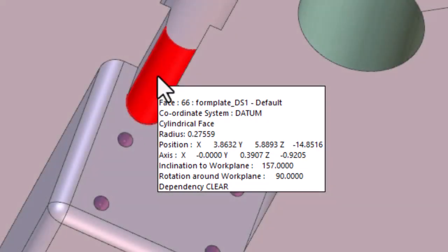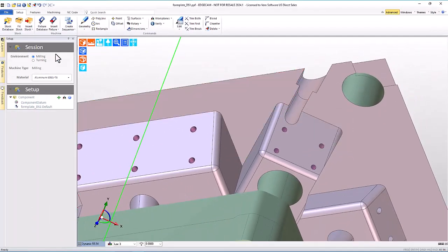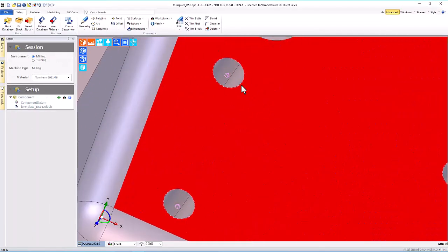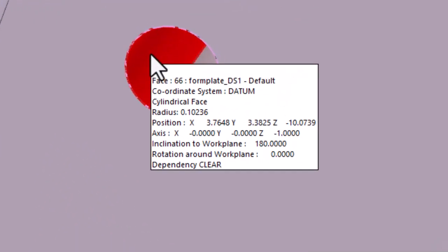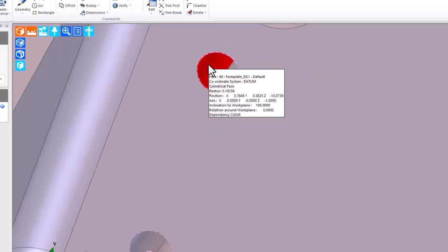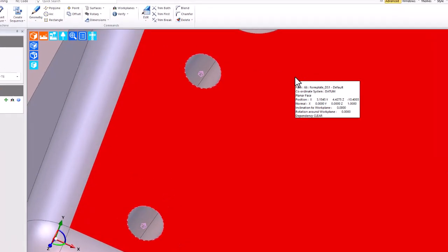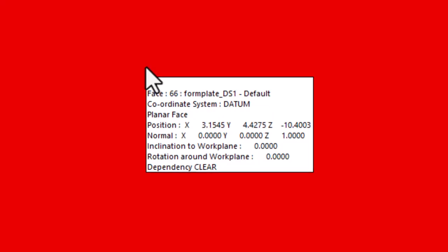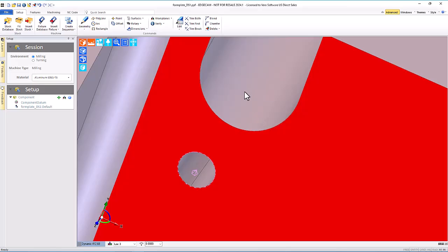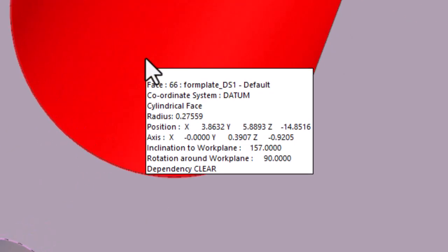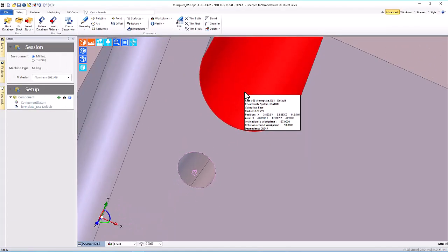The vectors split somewhere else, but it's not in the z-axis of the current plane. If I hover over the holes that we did find features in, their axis does have the hole number in the z-axis because they are parallel to the z-axis of our plane. This face has a normal representing perpendicularity, again with vectors, and this face is perpendicular to the plane, but this cylindrical face does not have an axis lining up to this plane. We will need a unique workplane.